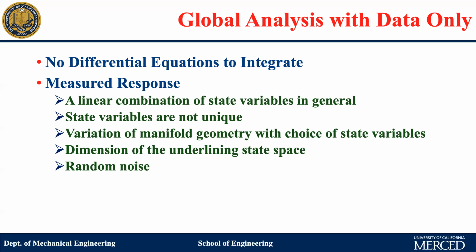So we don't need differential equations anymore. We only rely on measured response. And then we have to point out the measurement usually is a linear combination of the state variables. And you don't know what state variables are because you don't have equations, right? And also state variables themselves are not unique. So you only rely on the data. Okay, therefore, it depends on how you formulate some state space representation from the data.